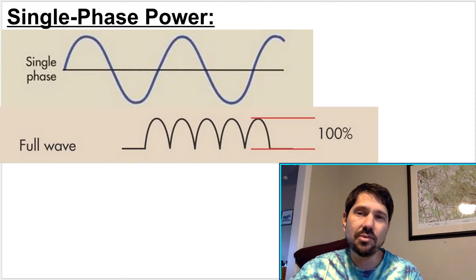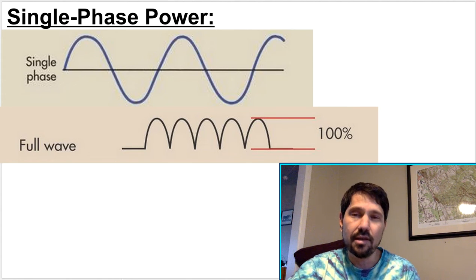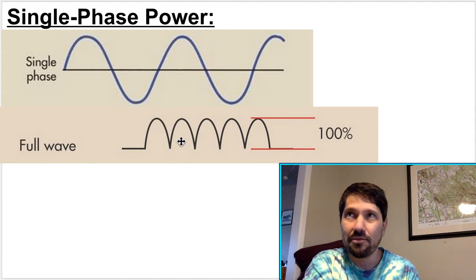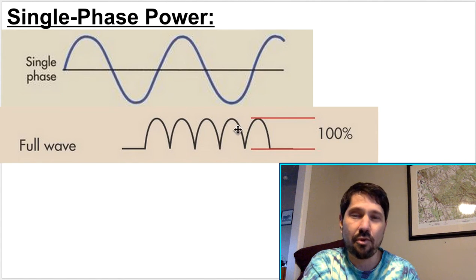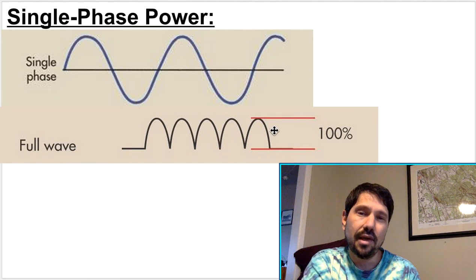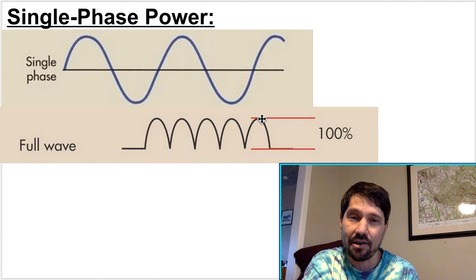phase. And the reason we do that is, if you remember, single phase looks like this, feeding our circuit. And by the end of our circuit, after we've gone through our bridge diode rectifier, we have 4 diodes fully rectifying this single phase waveform such that we end up with this waveform that's going on and off as our voltage across the tube or as our radiation output from the tube. And you see we have 100% ripple. Sometimes we're at 0, sometimes we're at the desired kVp.